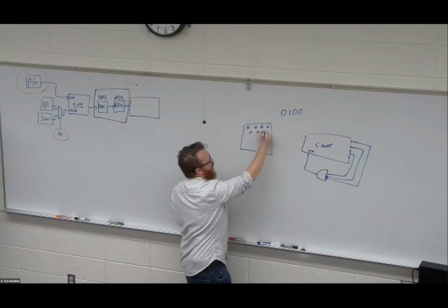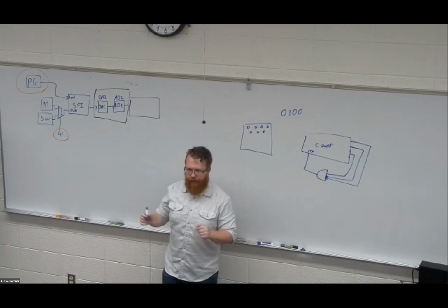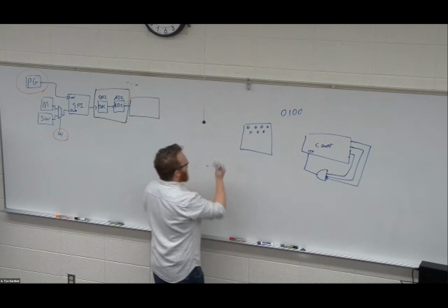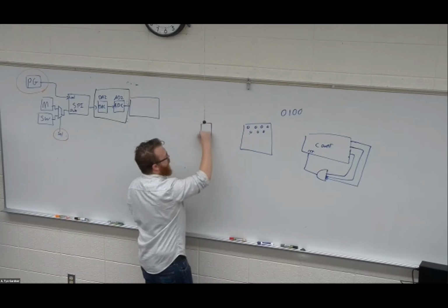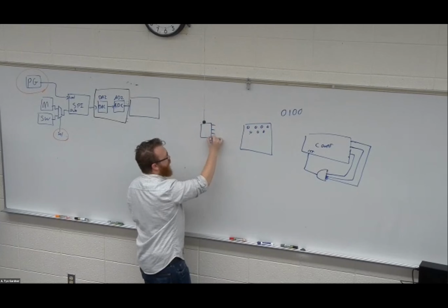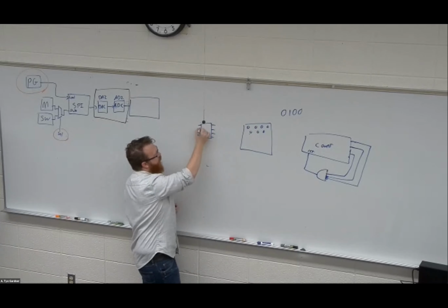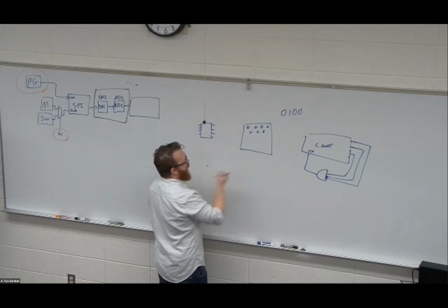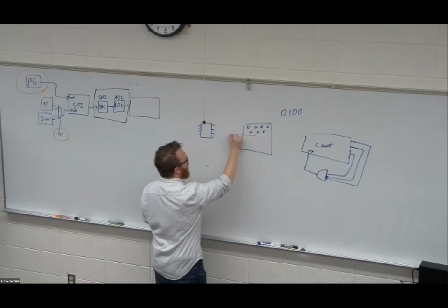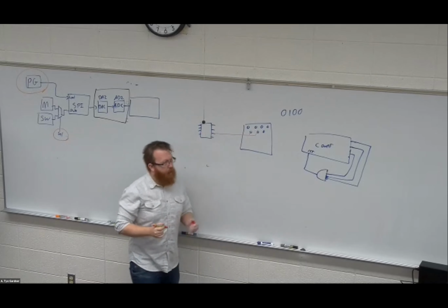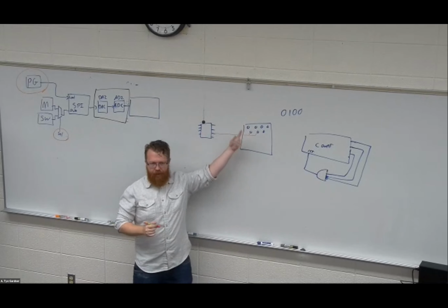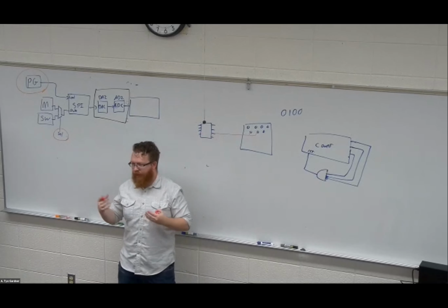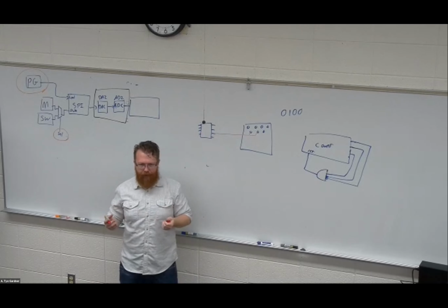circles on the bottom that have the traces coming out, right? So when physically implemented, if I wanted to go talk to an ADC over here that looks more like that, right, with the little legs, then I would have a trace that comes out and over and plugs in, right? But you can see that I'm limited to some number of IOs. I can't have infinite IOs, so I have to take that into consideration when I'm building a device.